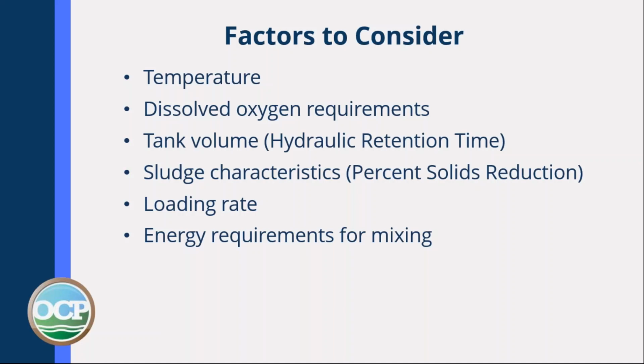Tank volume: your tank must be big enough to hold the sludge that you're trying to treat. Sludge characteristics: you have to know what percent solids reduction you can hit with your particular sludge. Loading rate: how much sludge you can add to your tank. And the energy requirements for mixing. You must have a mixer capable of stirring the sludge.